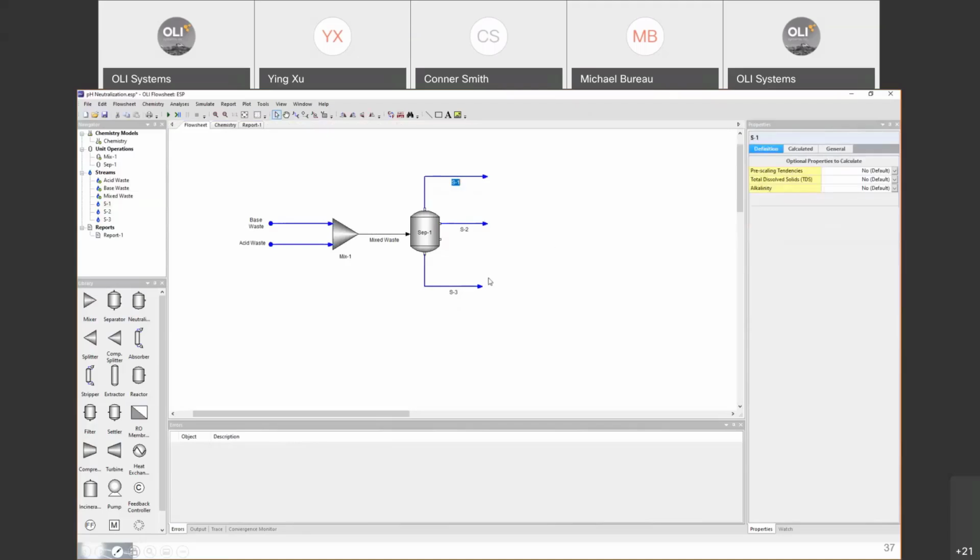Let's rename these streams. This is going to be the SEP vapor. SEP vapor means the vapor that comes from the separator, then SEP liquid, and double click on here to name this SEP solid. Please let me know if I'm going too fast, or maybe too slow, so I can speed up. Okay, so that is regarding the separator.